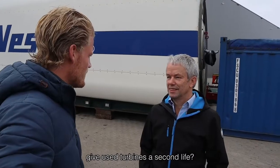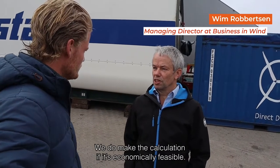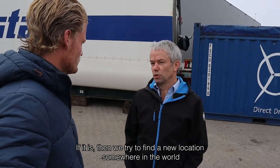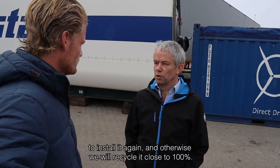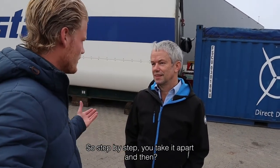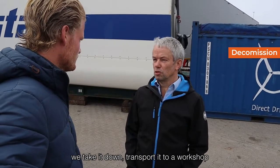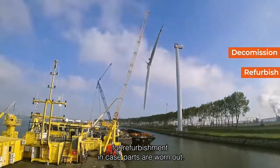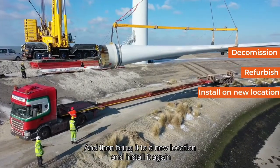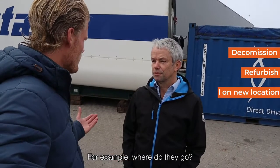How does Business in Wind give used turbines a second life? We do make the calculation if it's economically feasible. If it is, then we try to find a new location somewhere in the world to install it again. And otherwise we'll recycle it close to 100%. Alright, so step by step you take it apart and then? Yeah, we decommission, we take it down, transport it to a workshop for refurbishment in case parts are worn out. And then bring it to a new location and install it again and make it operational for another 15 or 20 years. And for example, where do they go?